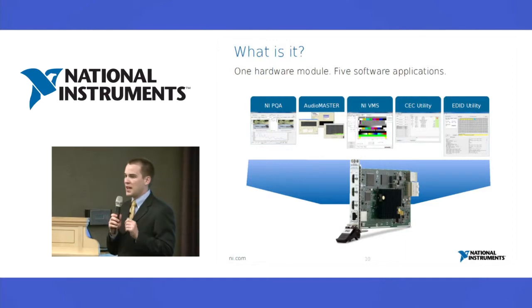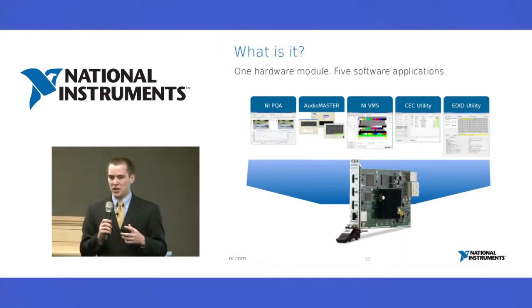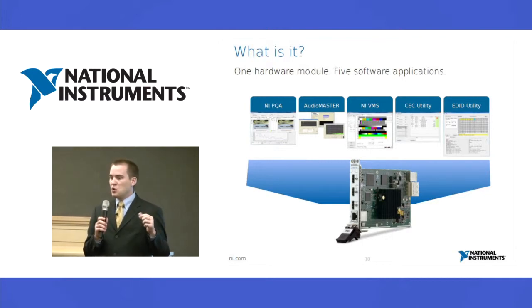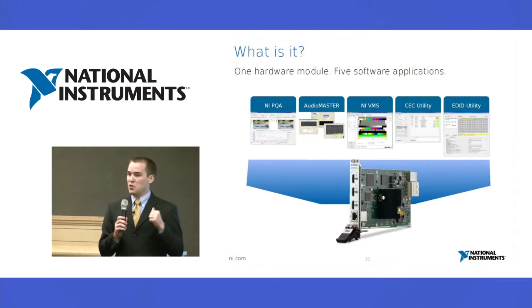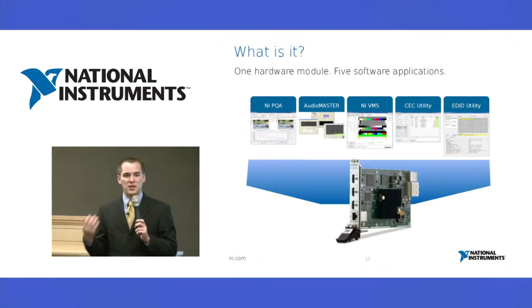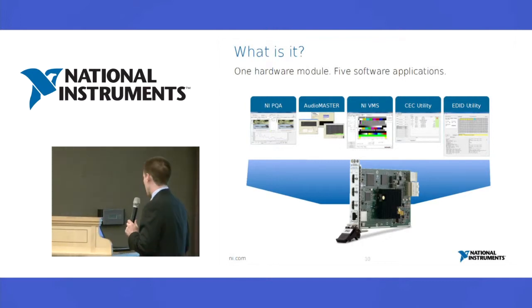And the last one is that HDMI embedded Ethernet channel, the HDMI Ethernet channel, HEC. We also have a hardware breakout of that. So if you have an HDMI device which is using that Ethernet network inside the HDMI cable, you can break it out and test it using this. You can do ping to make sure it's working. You can do stress testing, standard network test through this breakout.